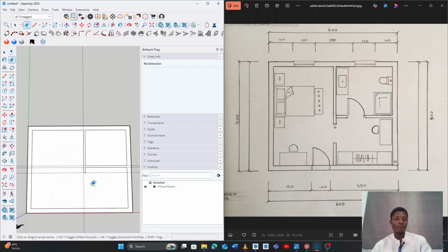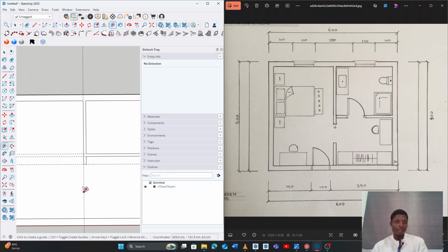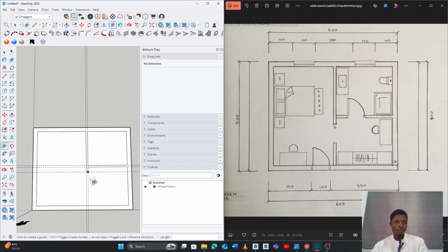we are currently working on. Okay, so on the other side of the dressing area where your wardrobe would be, there is a wall over that side. So we are going to pick our tape measure and left click on it. See on the guidelines over here, we already have a guideline telling us that our wall has to be on the same side as this wall. So I left click once and put it onto that wall so that the thickness will be the same. Then I zoom out a little bit.